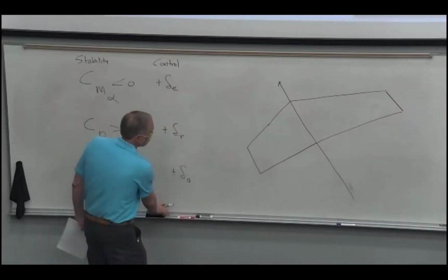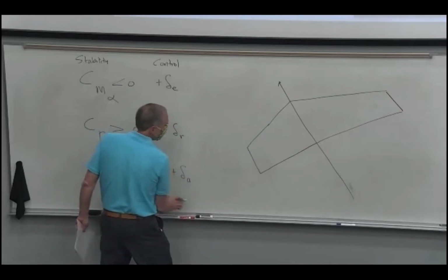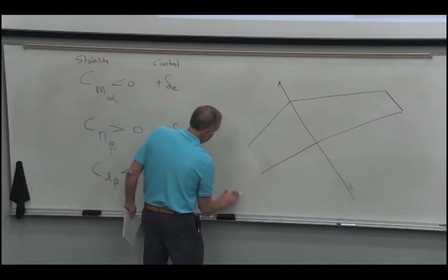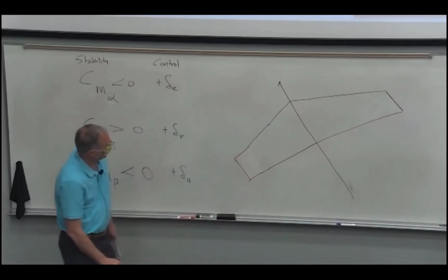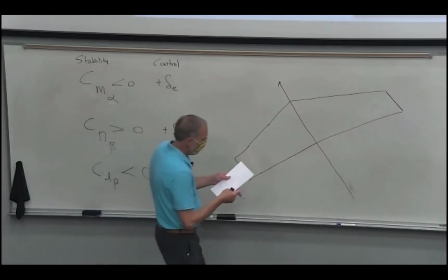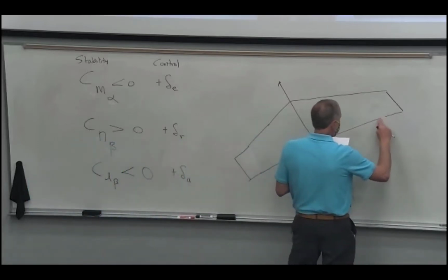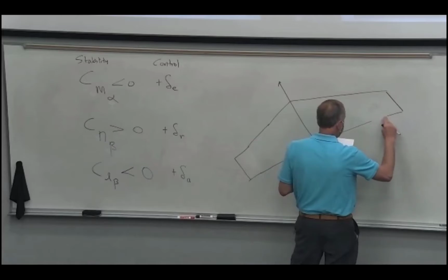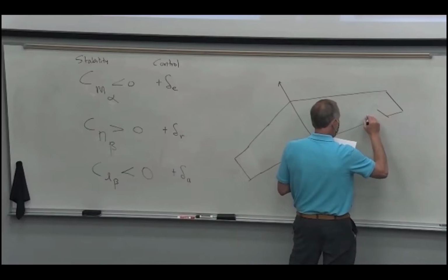Well, my airplane's going to flip because it's not symmetrical. So let's make the wing a little longer here. Does that look better? All right, so ailerons are flaps that are added outboard so that there's a long moment arm to allow this flap to act.